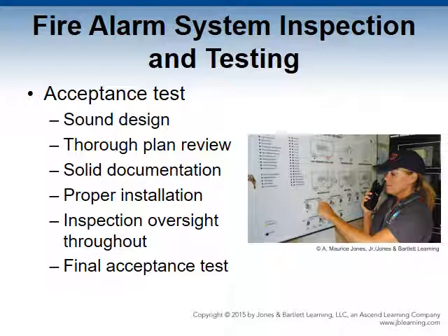Functional testing requires that the device be put through an actual operational test, not a simulated test. When an existing system is repaired, modified, or added to, NFPA 72 specifies testing 100% of the devices directly affected by the change, and testing 10%, up to 50 units, of the existing initiating devices not affected by the change.